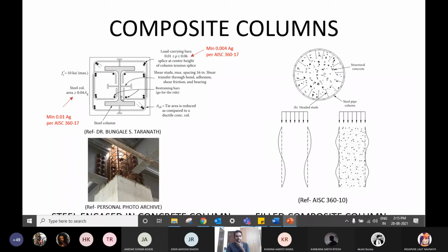So these are the shear studs, and there are some ways in which you can place them, and the spacing will be in the vertical direction. It could be 300 mm or 200 mm, whatever is there as per the design. Now you have some reinforcement bars inside as well. That also needs to be tied up. Basically, every reinforcement bar needs to be tied around using a tie bar. Something needs to run along with it and cover it. That's why we have these tie bars.